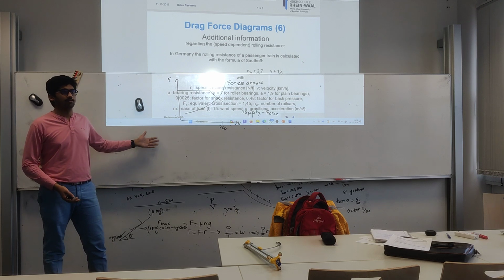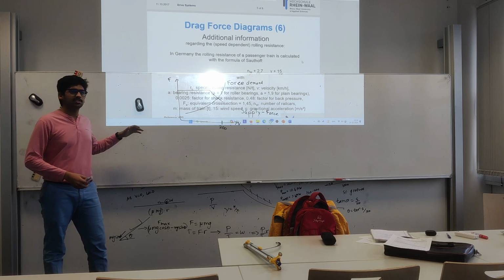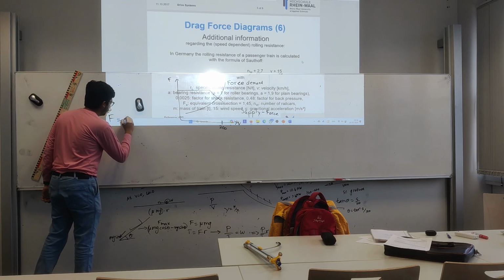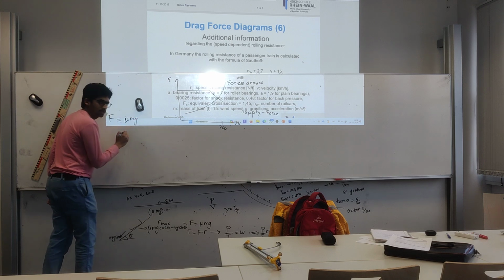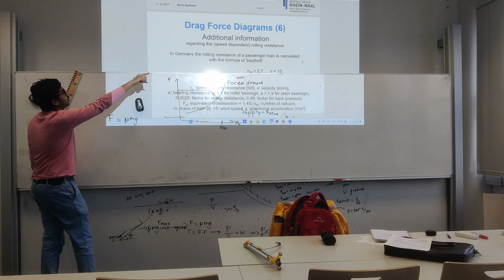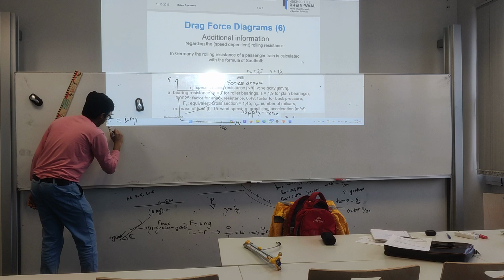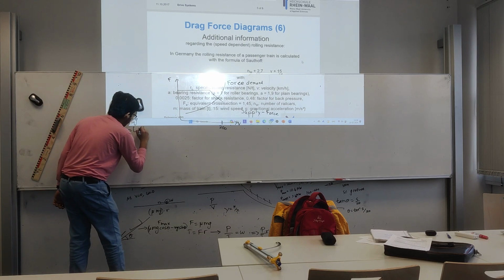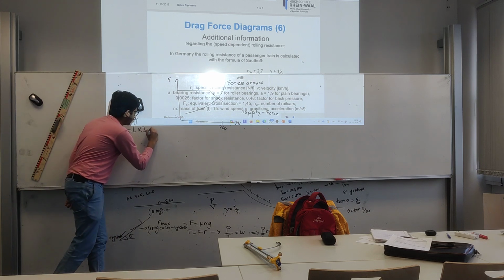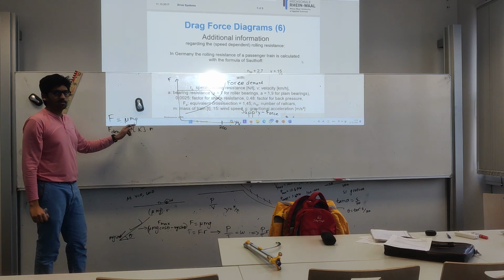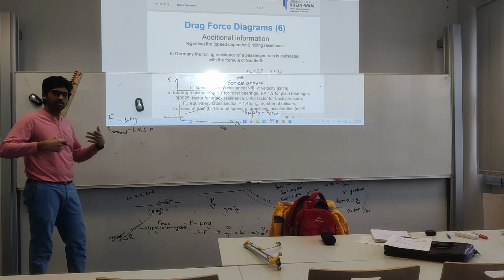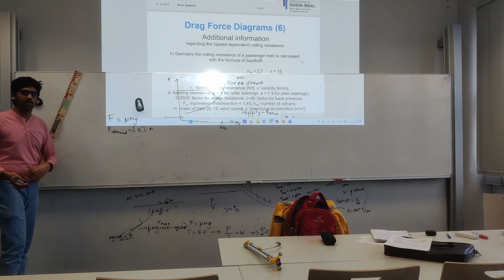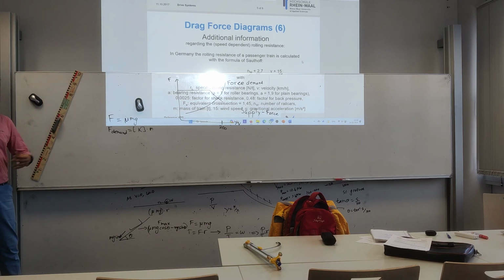In those kinds of trains, it's beneficial to decrease mass because the drag force F is mu mg, right? The force demand, as per Davis, is going to be some k for that speed multiplied by m. So when you divide them, the masses cancel out, and it's in your interest to decrease the mass. Sorry, just additional information. That's why the configurations between passenger trains and goods trains are different.